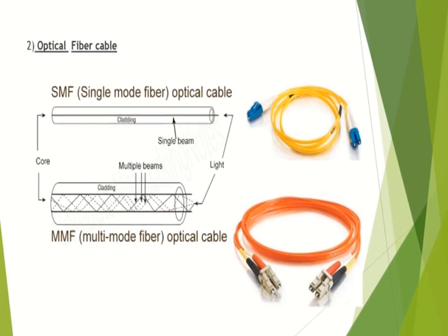An MMF cable has a large core diameter and is able to accept a number of different modes that come into the cable from multiple angles, while SMF has a much smaller core diameter and accepts signals coming in from a specific angle and on a specific mode. SMF can be used for cable runs of very long distances, typically up to 40 miles without repeaters, depending on